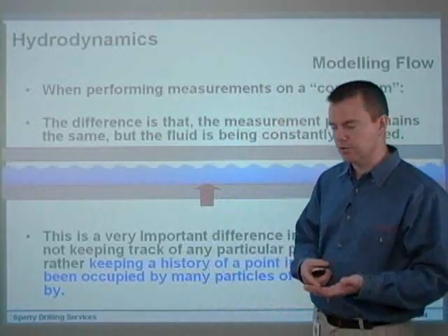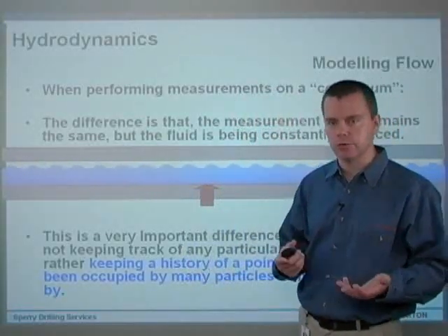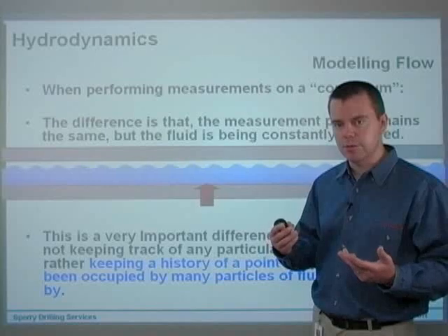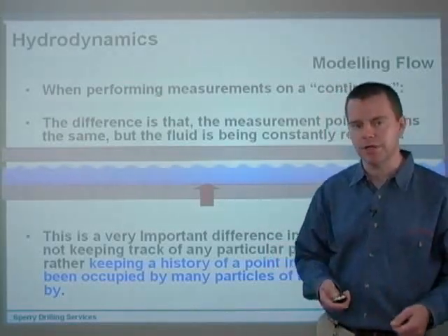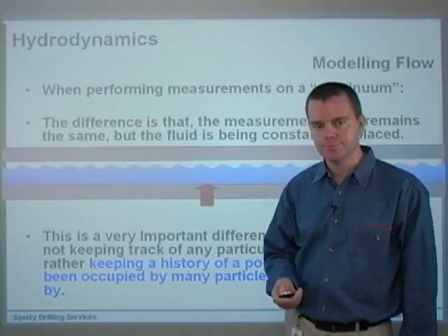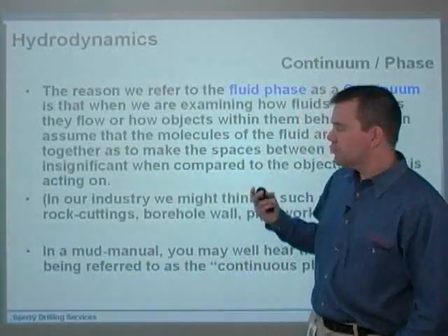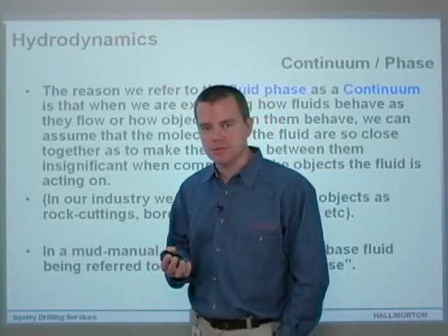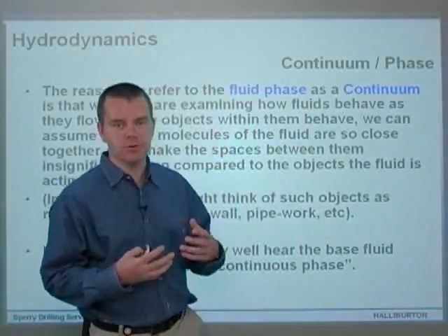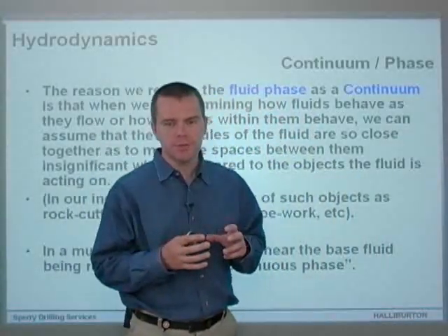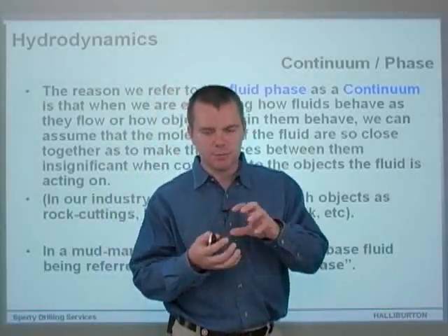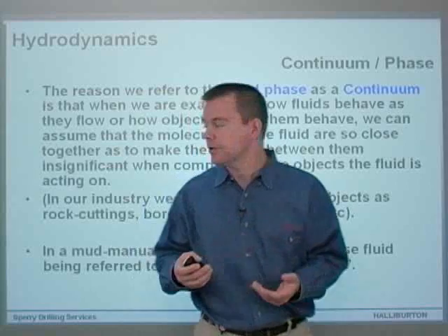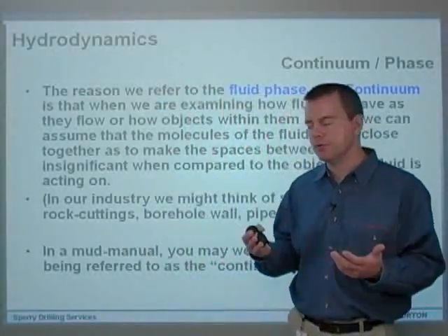We still end up looking at forces and accelerations and velocities and so on, but they're measured and modeled in a slightly different manner. And it's important to bear that in mind before we go any further. The reason we refer to the fluid phase as a continuum is that when we're examining how fluids behave as they flow, or how objects within them behave, we can assume that the molecules of the fluid are so closely packed together that the spaces between them are insignificant when compared to the size of the objects that are held within them.